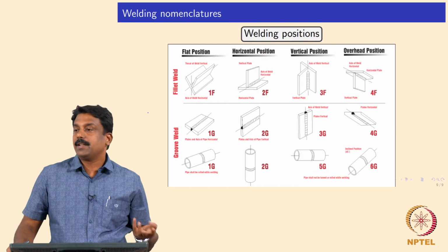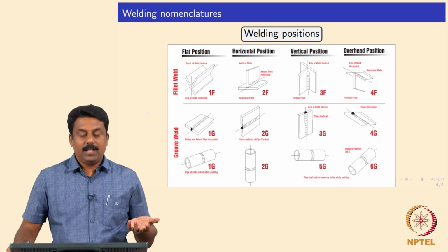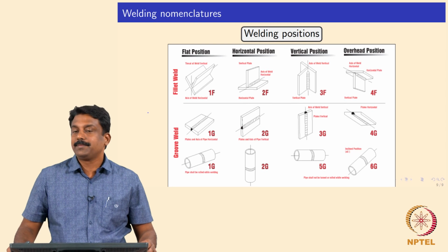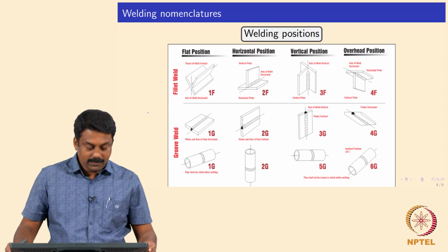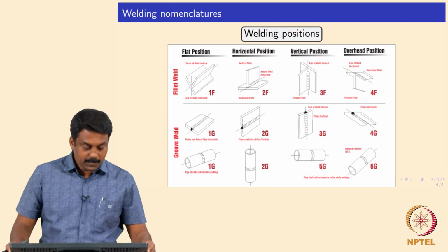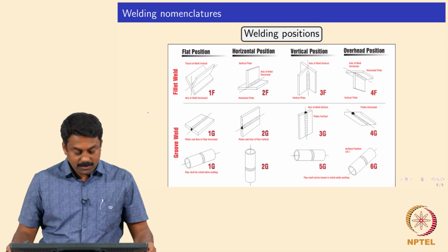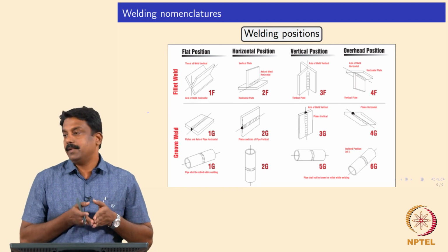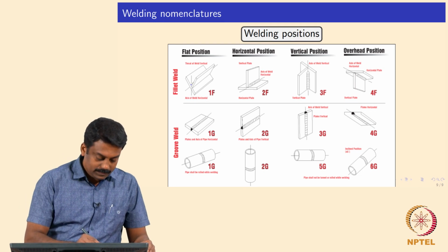And there is more defined terminology by the International Institute of Welding, so we use G's and F's to denote the welding positions. The F denotes fillet weld, but based on the position we can say 1F, 2F, 3F or 4F. So, what is 1F? 1F is a down hand weld, you make a fillet. So, something like this.